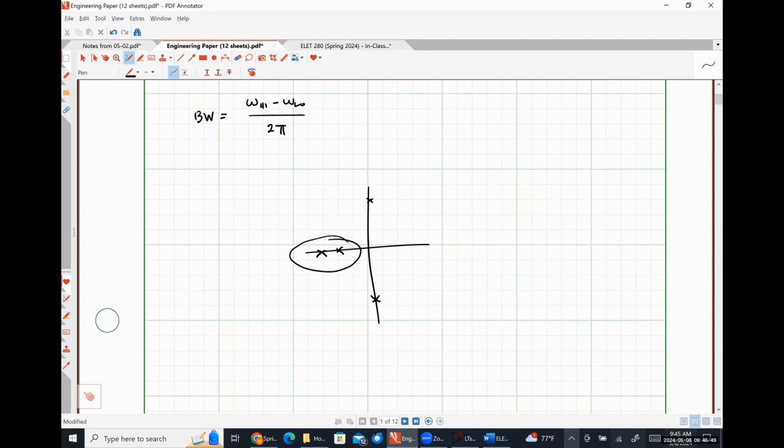If we want all of those poles to be negative, we're realistically only looking at their magnitudes, because what does a negative frequency actually mean? Nothing. It's impossible to get a negative number using the short circuit time constant method or the open circuit time constant method, because everything you're putting in is positive. So comparing magnitudes is exactly what you could be doing.